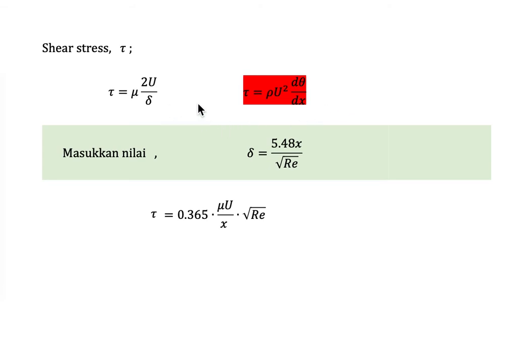To calculate shear stress, I advise you to use the equation from Newton's law of viscosity, because in it the value of tau is fully developed. In the von Karman equation, the term d theta over dx shows that this equation is not fully developed, so we cannot use it for further investigation. Please remember, use the shear stress equation from Newton's law of viscosity.